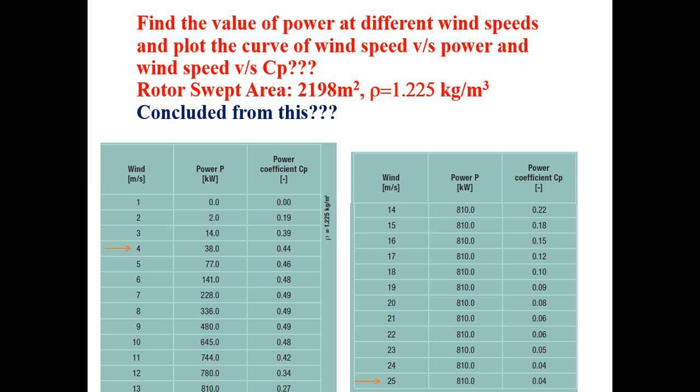So after reaching the rated wind speed, the blade pitch angle, that is beta, is going to be activated, known as blade pitch control. There are blade pitch motors. Wind speed would be sensed by the anemometer, and it is communicated to the pitch motor, and pitch motors are activated after rated wind speed. Now if you talk about the Cp, this is the almost constant Cp region. See how it deviates from 0.59. These are the other losses that could be encountered by the wind turbine.